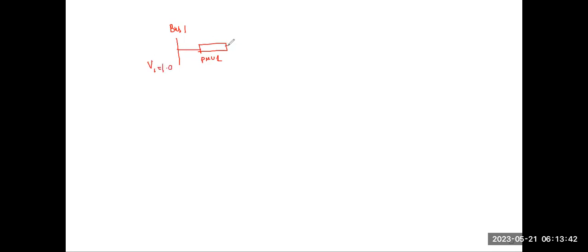Then this is the transmission line. This transmission line has an x value of 0.1. The magnitude part of this would actually mean 0.1 at an angle of 90 degrees, because j means 1 at an angle of 90 degrees. But now we are not interested in that angle part, only the magnitude part in this calculation.